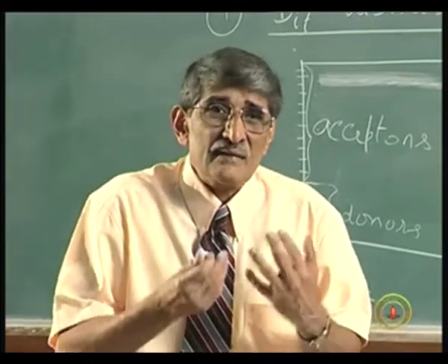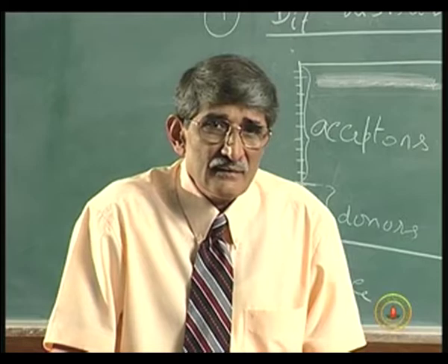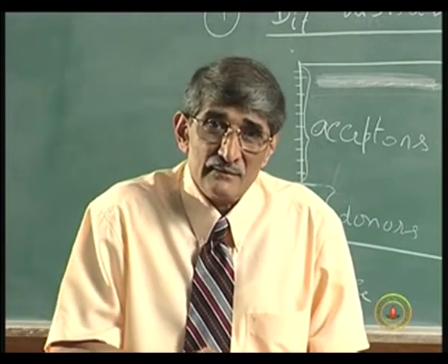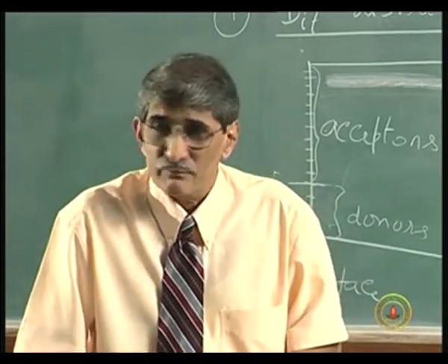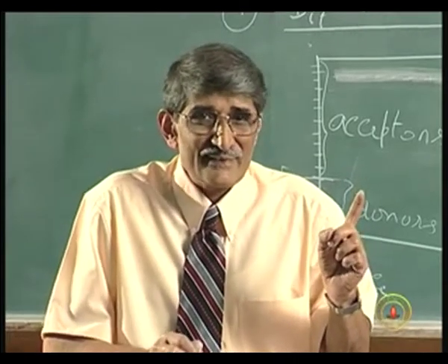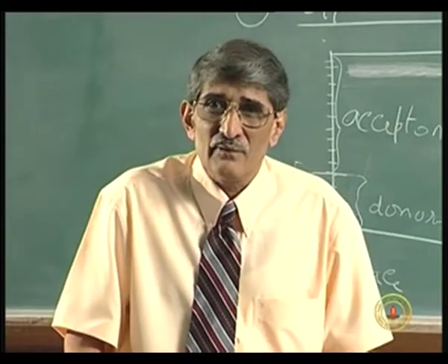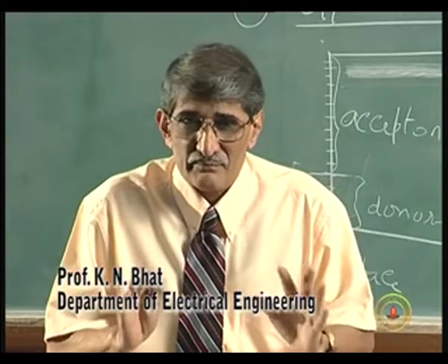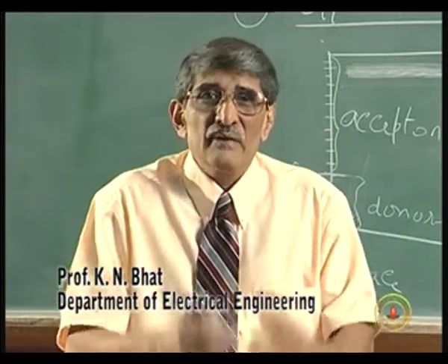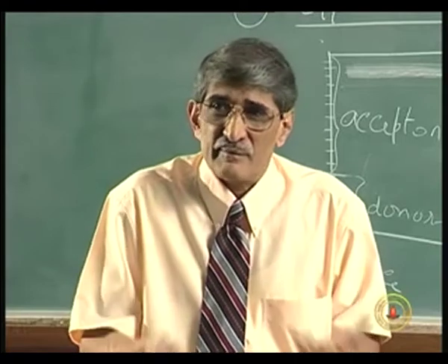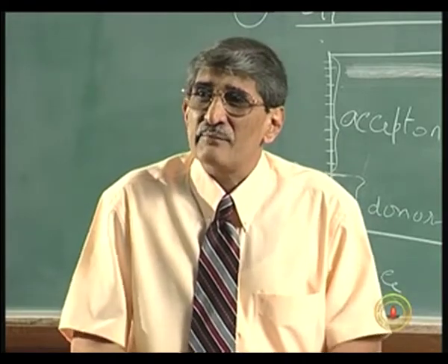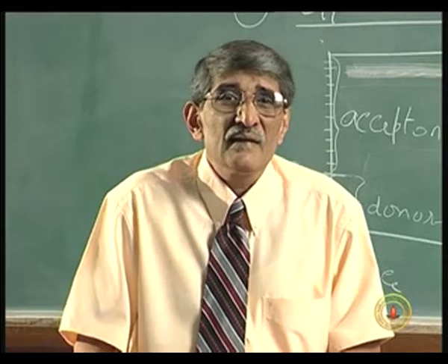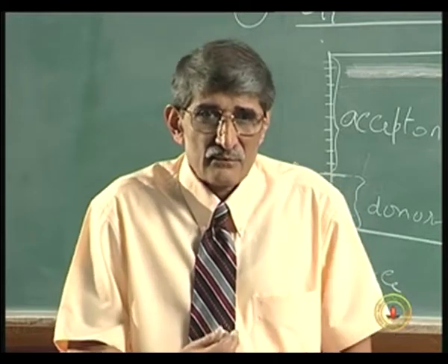When you say an acceptor is ionized, it has accepted an electron, but donated a hole to the valence band. Both are donors, if you look into it. One donates electrons, one donates holes. One donates negative charge, the other donates positive charge. That is the key. So, when the donor level donates electrons, it becomes positively charged. When the acceptor level donates a hole, it becomes negatively charged, because it takes an electron.